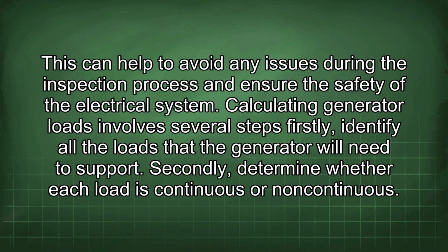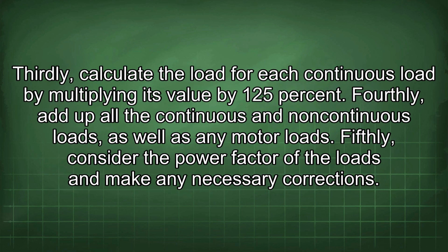Calculating generator loads involves several steps. Firstly, identify all the loads that the generator will need to support. Secondly, determine whether each load is continuous or non-continuous. Thirdly, calculate the load for each continuous load by multiplying its value by 125%.